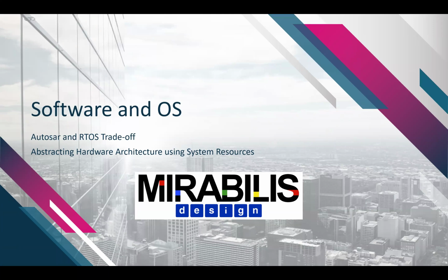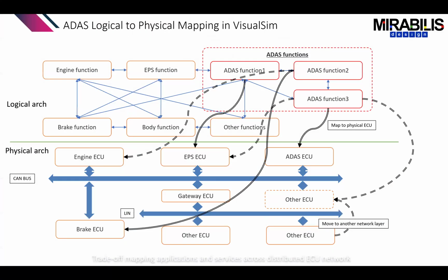virtual operating systems? One of the key things when you run anything with software is to determine the level of abstraction you want to use. The reason is, if you put in too much detail, simulations will run extremely slow. If you don't put in enough detail, the results will not be correct. So you have to have a trade-off between accuracy and the level of abstraction that you use.